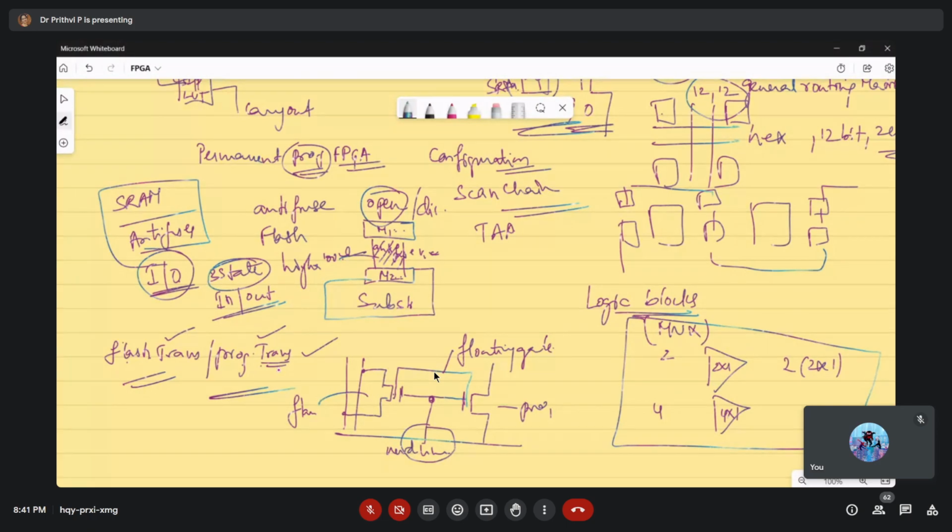Okay, and for all this, the interconnectivity and all, we have to go for what is called placement and routing. What is placement? In a provided space, how many logic elements are there and where should I place them is the point of concern. That is placement: deciding the positions of the logic elements on a given space to efficiently occupy the given space. That means there should not be much wastage, or it should not take more space than provided. That sort of aspect we have to see.